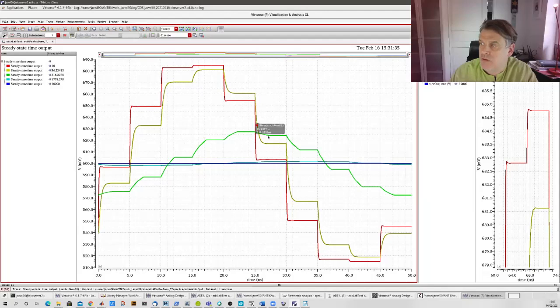And there you see it starts struggling. And also the yellow one is struggling because it doesn't reach the end value. So the settling does influence the result, even though it's a low number, only 60 ohms, which is not much. It sort of looks fine. It looks like it settles, but actually if you look at the whole scale, you lose amplitude here and accuracy if it would be a data converter. And the green one is sort of beyond help then.